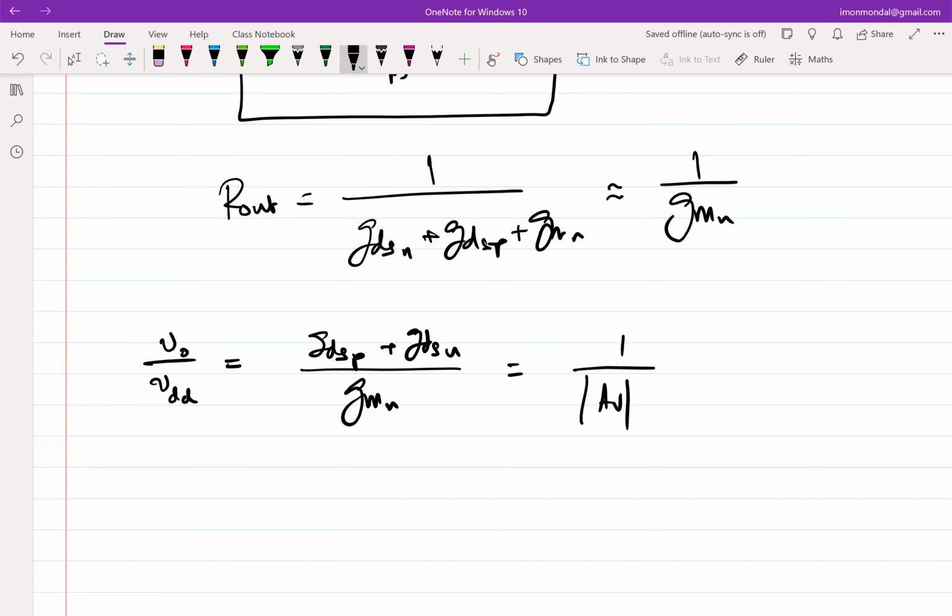Okay. So essentially this is the definition of PSRR: V naught over VDD under open circuit condition divided by the gain. Right. So that's the standard definition of PSRR. And the reason that is an acceptable standard definition is because you don't ever use your circuits in open loop, you use it in closed loop.